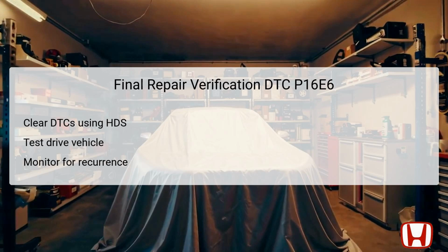After conducting the necessary repairs or replacements, it is vital to perform a final verification process to ensure the issues associated with DTC P16E6 have been resolved. Begin by clearing the diagnostic trouble codes using the HDS to reset the system. Following this, conduct a test drive of the vehicle to validate that all systems are operating normally, paying specific attention to the transmission's performance during different driving conditions. Throughout this testing phase, remain alert for any persistence of warning indicators or issues, as this would suggest that further diagnosis is necessary to ensure the reliability of repairs made.